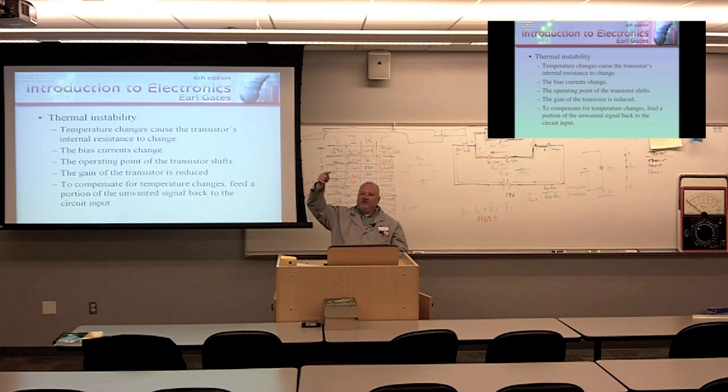If we were at saturation and we put a signal into it, any change in that input signal wouldn't be felt because the transistor is running at full throttle. But what's making the transistor more on or off is the depletion zone, right? Correct. And that depletion zone is changing based on the input signal of, like, you speaking into a microphone.